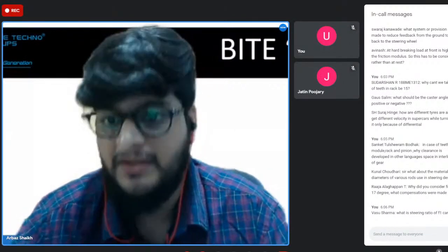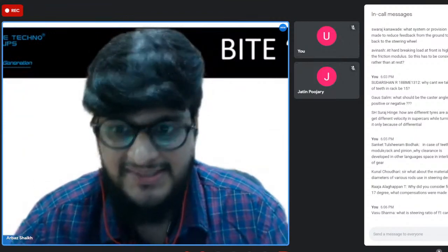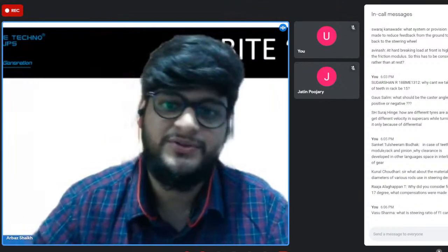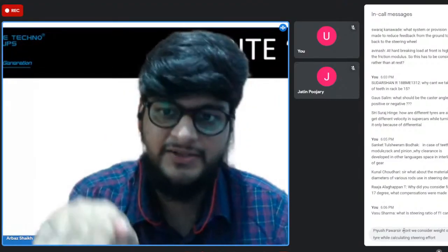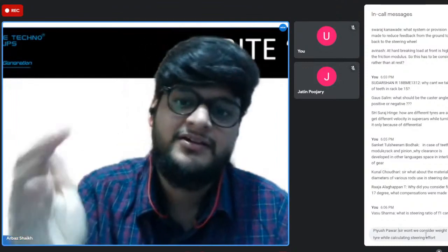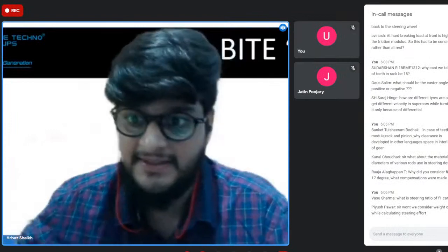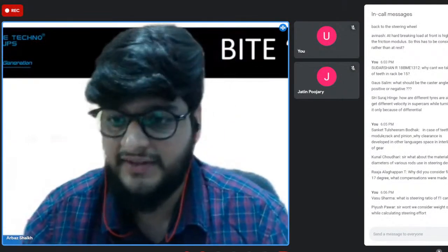friction will be maximum. Avinash, tell me, when you apply a hard brake, can you turn your vehicle? That's my question to you, because the vehicle will be drifting in a straight direction and you cannot turn it. If you move your steering wheel, your vehicle will not turn unless you have ABS. And if you have ABS, your vehicle will be in smaller motions and your effort will still be lesser than what it was when the vehicle was at rest.